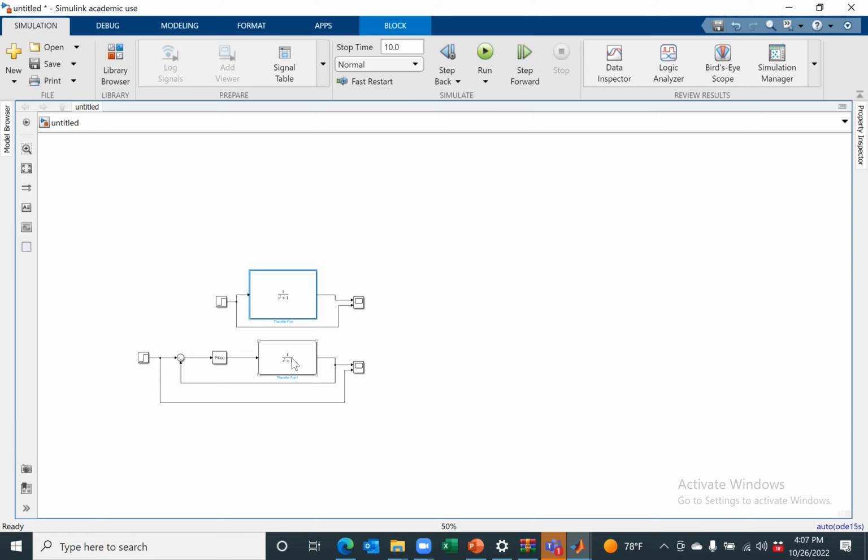And that is where the derivative term comes in the picture, which means now the controller effort is dependent on the derivative of state, not only how far your friend is, but how fast you are approaching him. Everyone understood this? That is the derivative part. Now, what is the issue with proportional and derivative?